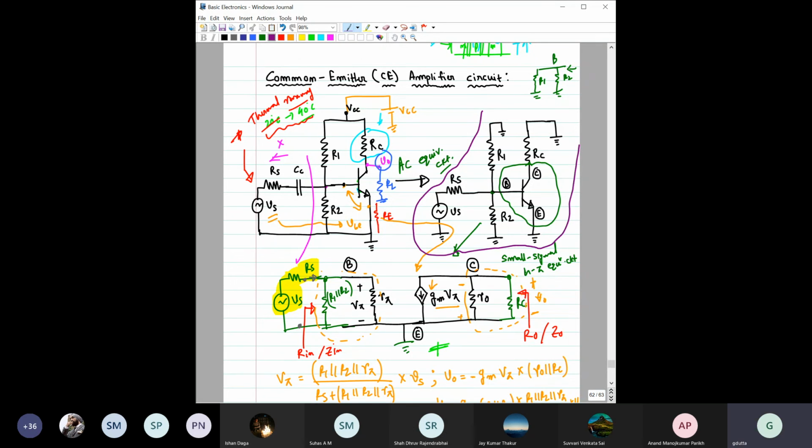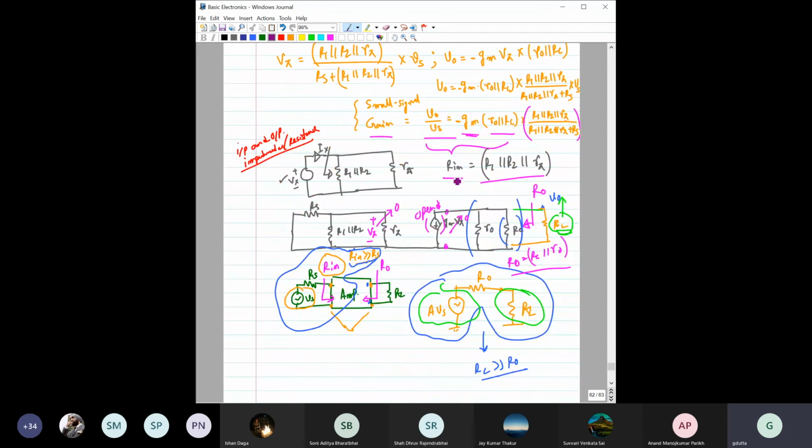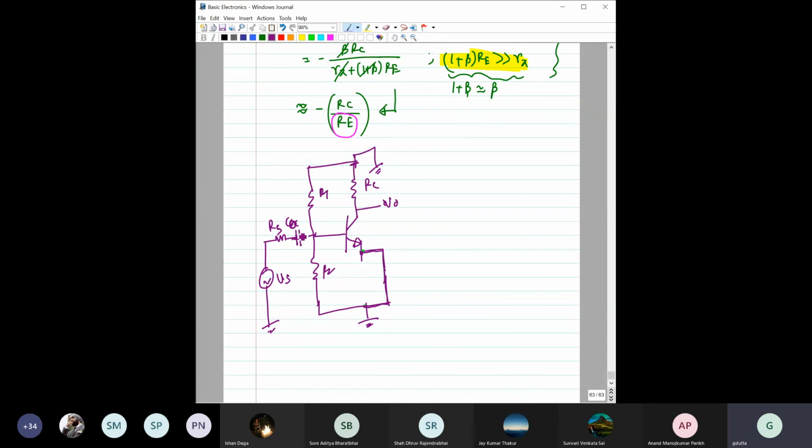But sir, we are considering small signal gain, right? Then what is the use of adding it? In case of small signal gain, both the circuits are the same. Then how will it provide stability? Because RE is not considered in both of the AC analysis cases. Yes, but please try to understand what we are trying to point out: during DC analysis, this RE would provide the stability.